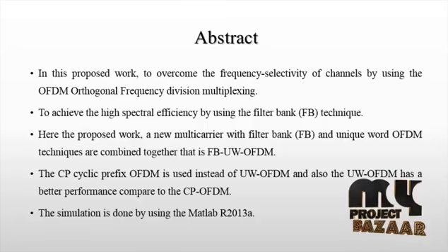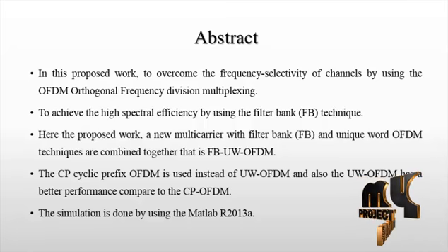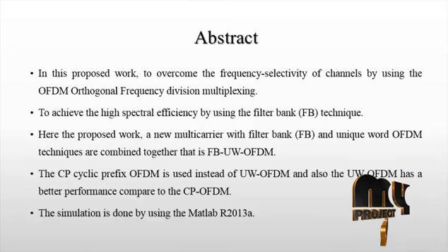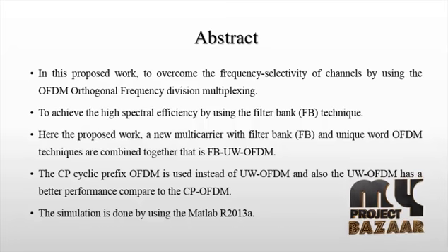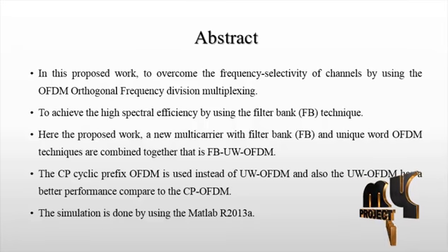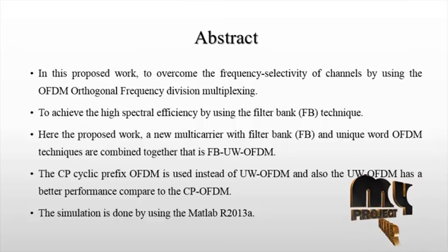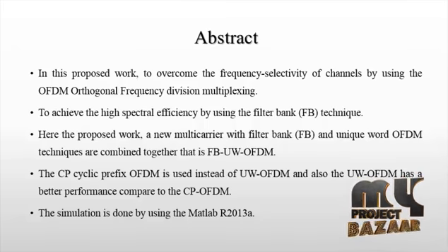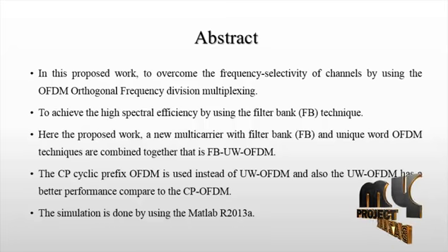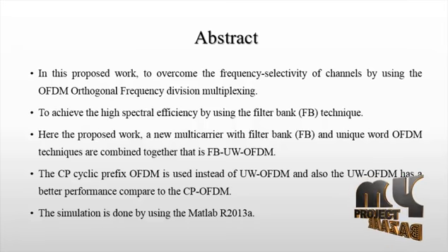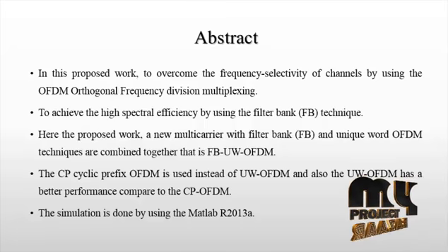The MIMO concept, the multiple antennas in a MIMO system, can be explored in two different ways. One is the creation of a highly effective antenna diversity system, and the other is the use of multiple antennas for the transmission of several parallel data streams to increase the capacity of the system. Antenna diversity is used in wireless systems to combat the effects of fading if multiple independent copies of the same signal are available. We combine them into a total signal of high quality, even if some copies exhibit low quality.